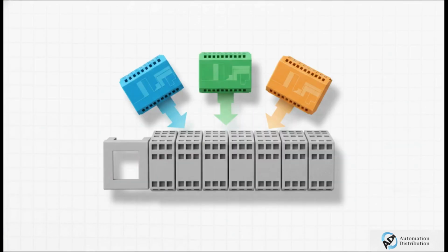Now, what if your PLC is remote and you just need remote I/O out in the field? Well, you absolutely must match the fieldbus coupler perfectly to the native protocol of your network. The cleanest way to guarantee that compatibility is by using a modular I/O backbone, like the Wago 750 system. The real beauty here is that you don't have to rip and replace your entire I/O rack if the network changes down the road. You use the exact same I/O modules and you just snap on a different head, the coupler. Running EtherNet/IP? Snap on the 363 coupler. Need PROFINET? Grab the 375. Need that vendor-neutral Modbus TCP? The 362 is going to be your go-to.